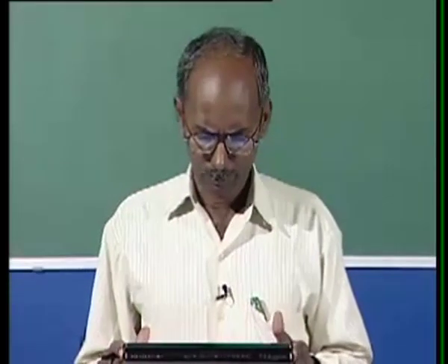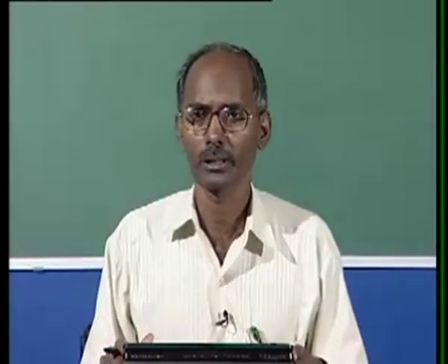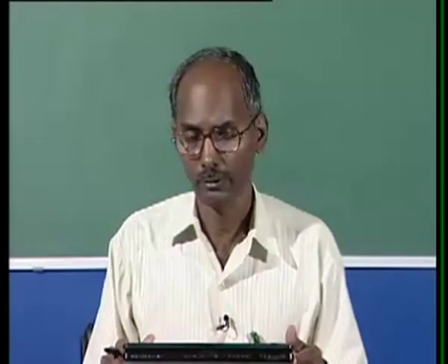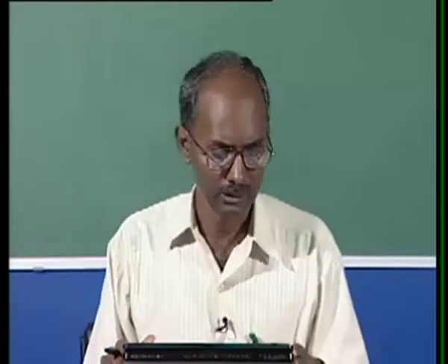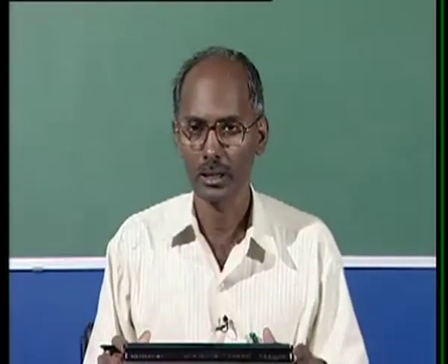Welcome to lecture number 4 of module 3. In lecture 3 we saw the static responses as well as the dynamic responses for the step change in the load, and there was some change in the frequency. We found that there is some steady state error, and that error has to be 0, so we have to take some control action, because our intention is not only to meet the load whenever it is changed. We also have to bring the frequency back to its normal or rated value.